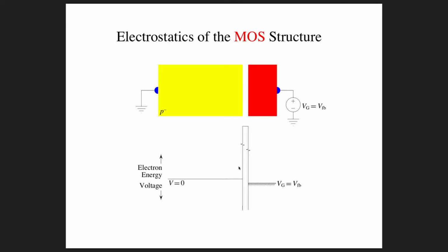And the average energy that an electron would have due to just thermal energy, its motion due to the fact that it's got some finite temperature and it's banging around with the lattice, would be kT, which is 25 milli-electron volts, or 1/40th of an electron volt.